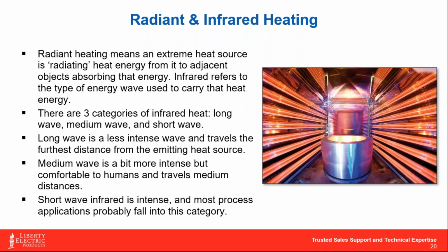Now, there's different types of wavelengths that we deal with in infrared radiant heating, and we've got shortwave, medium wave, and long wave infrareds, and there are certainly layers of separation in between, but the gist of it is that shortwave heat is typically very intense. It doesn't travel nearly as far as the other two wavelengths do, but it is an intense and harsh type of heat. So you can typically heat more with less when you're talking about a shortwave infrared. And it's probably the heater of choice if there's ever a threat of cold air intrusion into the space, or if there was ever a reason to do outdoor heating. That's your best bet with it.